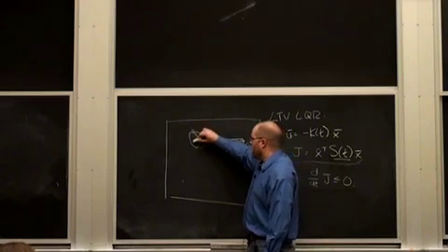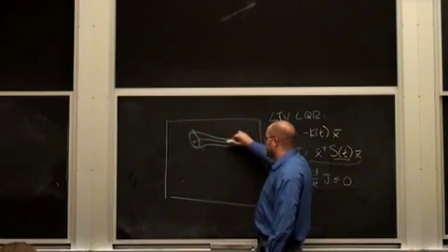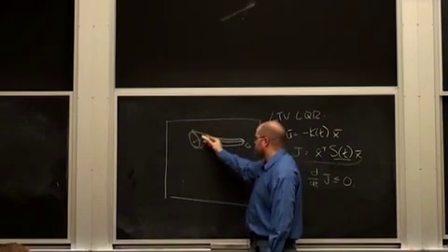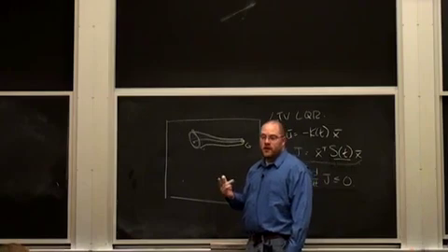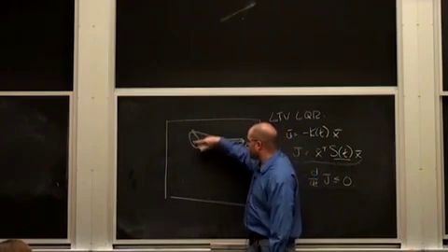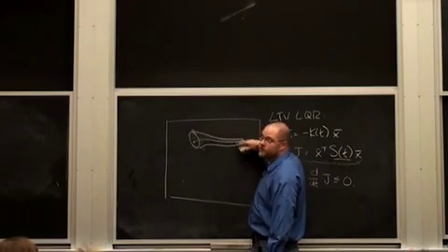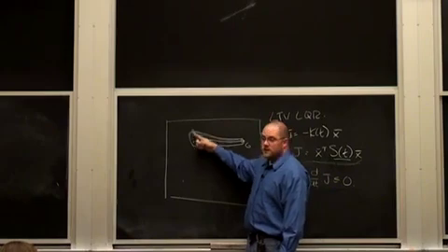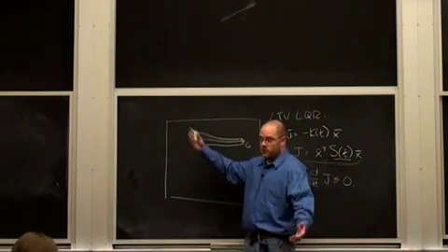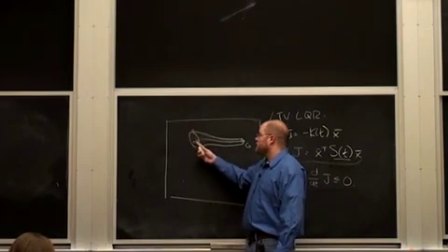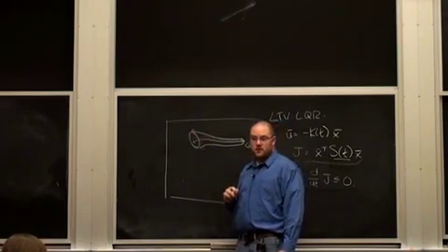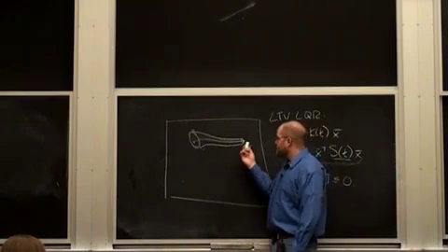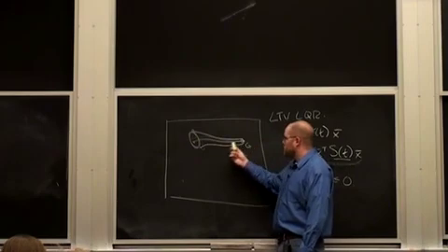The only weakness is that I'm only doing it by doing a polynomial expansion of the system here. So if there was a hard discontinuity right next to the trajectory that didn't show up in the Taylor expansion, then I wouldn't ever see it. I'm not exhaustively searching the nonlinearity around that trajectory. I'm just saying, along this trajectory, what are the higher order expansions? I do a Taylor expansion of a third order, fourth order, whatever it takes, and I use that to check when it breaks the cost to go, okay? So that's the certificate.